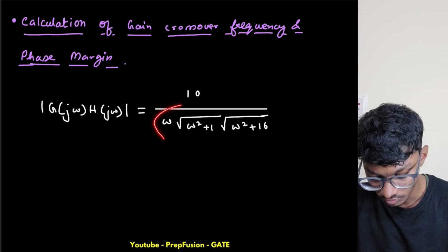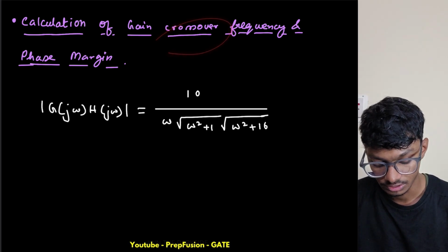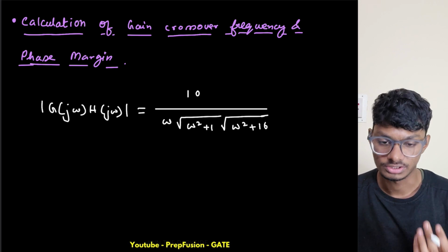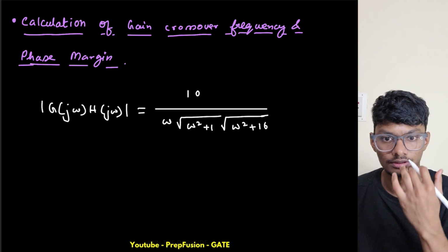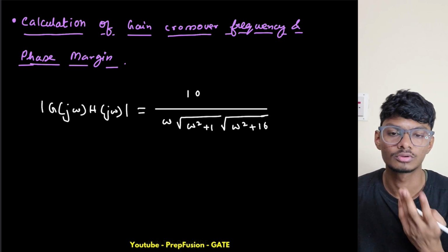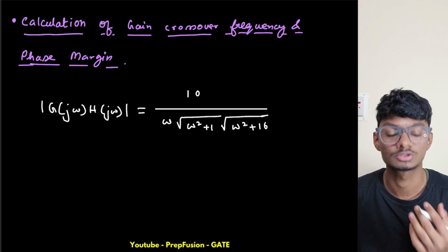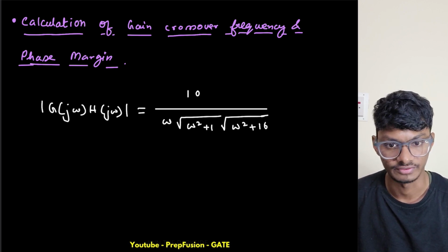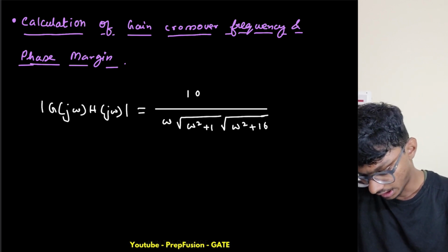If they have asked you to find the gain margin, the phase margin or the gain crossover frequency of a third order, basically this is a third order equation, right? Order is 3. You will get 3 roots. Hence what you will do is put a few standard values like plus 1, minus 1, all those things, and see that yes, I'm getting the value, because then only you will be able to solve it handwritten. Else solving a cubic equation manually is very difficult. You have to use online calculators, all those things. So yeah, I have also used this.